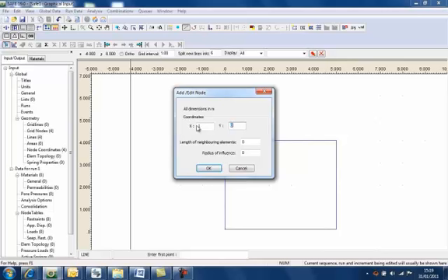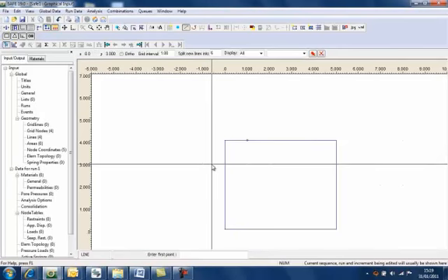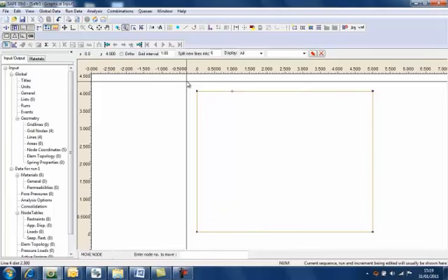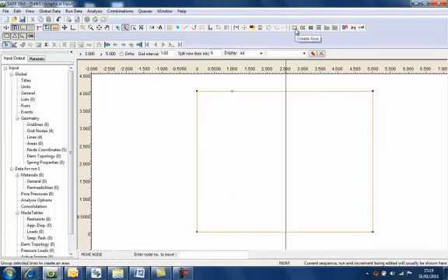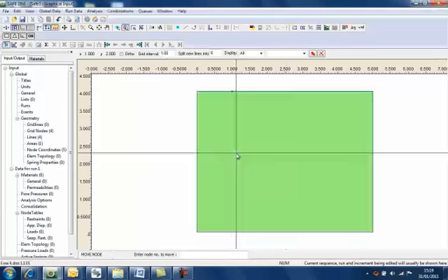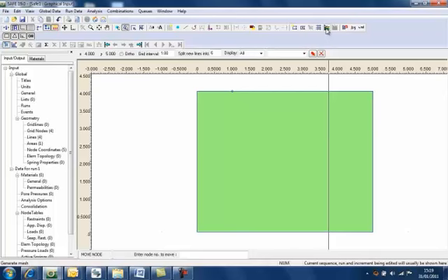Now, I've gone to adding a node, and the reason I'm going to add a node is that maybe, for example, I want to put a displacement point in a certain place, or something along those lines. I might need to put that node in. And by adding a node, I can actually refine my mesh, which is going to come up soon. So you select all the elements and you define an area. In this case, we've only got one material, but I could draw extra boxes for more materials and apply more materials, or I can choose specific elements within and change the materials.